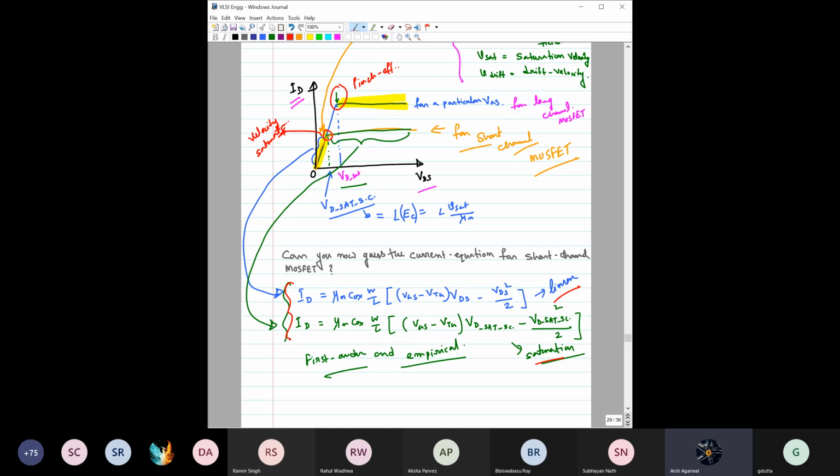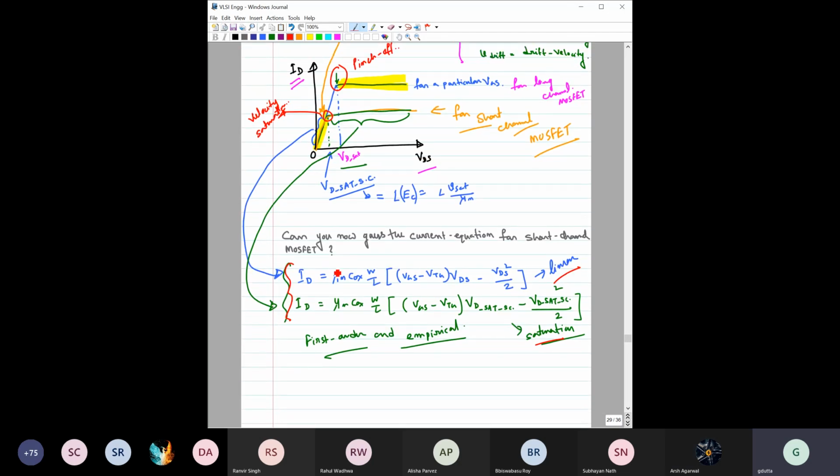Sir, what matters to us are the characteristics, right? What triggers those characteristics is not required in the final circuitry. If it gives the same characteristics, then it's the same for us. And that's what I'm trying to explain to you. If you put it this way, in saturation, what is the relation between ID and VG for short channel MOSFET? It is not a square relation here.